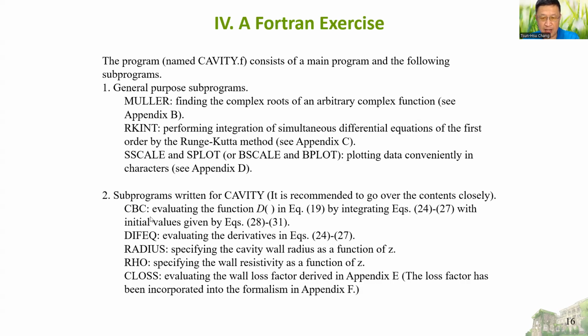Complex boundary condition: evaluate the function D of omega in equation 19 by integrating equations 24 to 27 with initial values given by equations 28 to 31. Differential equation: evaluate the derivatives of the four equations. Radius: specify the cavity wall radius as a function of z. Rho: specify the wall resistivity as a function of z.